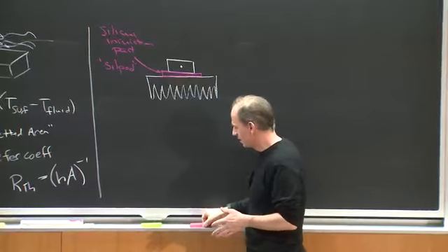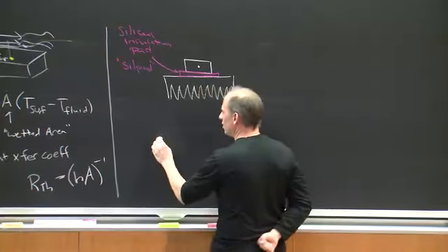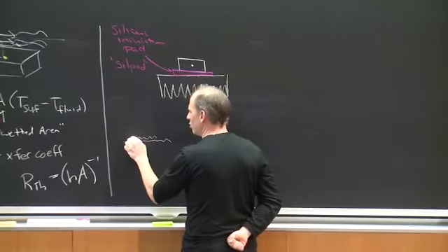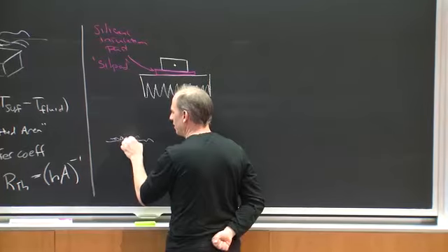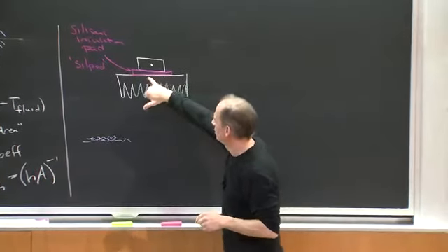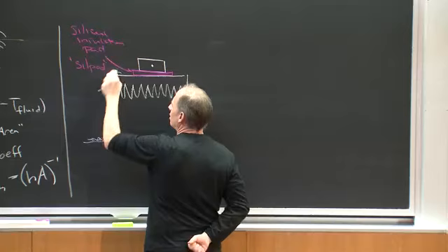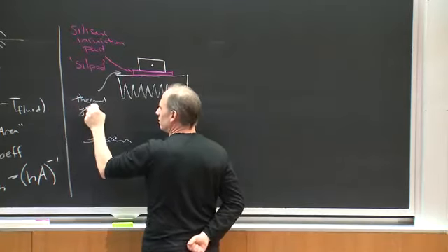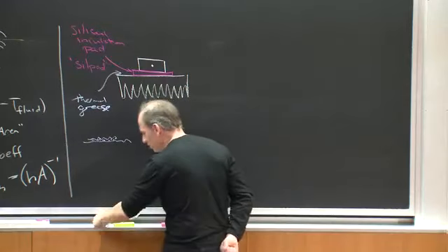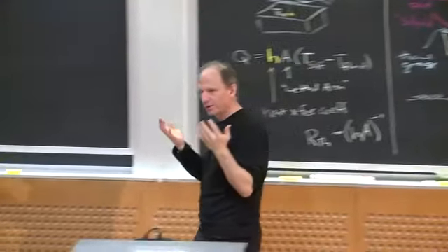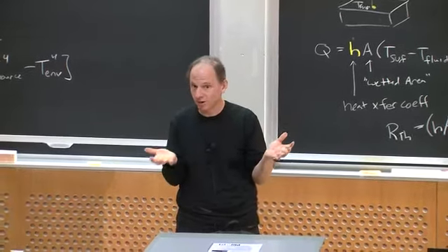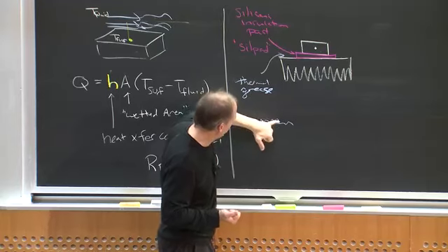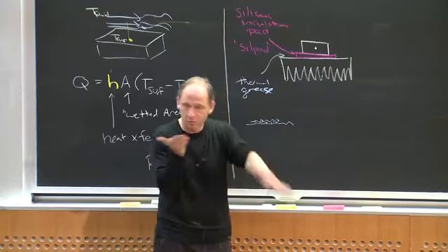Why? Because, if you think about surface roughness, maybe here's the back package of the device, and here's the surface of the heat sink. You don't want any air in between it. So in that case, what you might do is use thermal grease. So this could also be, instead, thermal grease. Okay. Why would I use thermal grease? Because thermal grease has a lot better heat transfer characteristics than air does. So you wouldn't want any scratches or open areas in the back of your device kind of limiting heat flow. So you fill that with thermal grease.